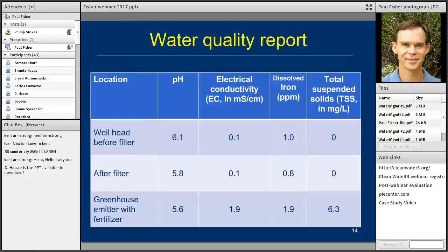These are the kinds of chemical tests we'll often run when we get a water quality sample into our lab. The pH levels are all moderate. If they're higher pH, it's quite often associated with perhaps high calcium, magnesium, and hard water, and perhaps we run into a chemical problem.